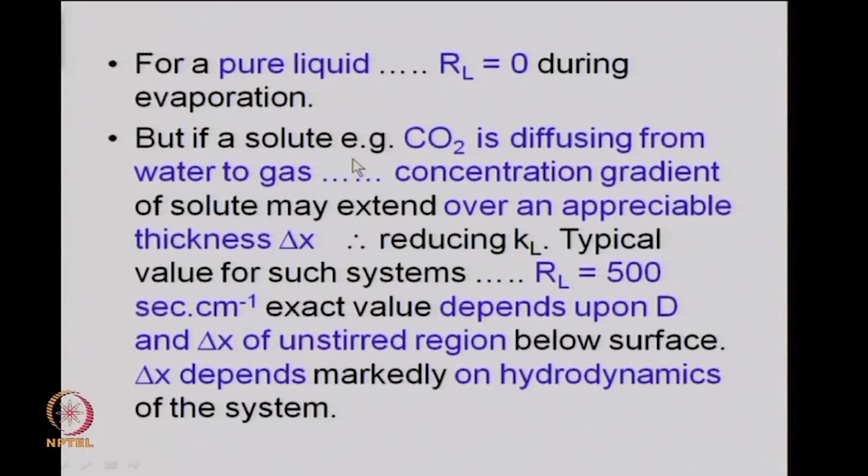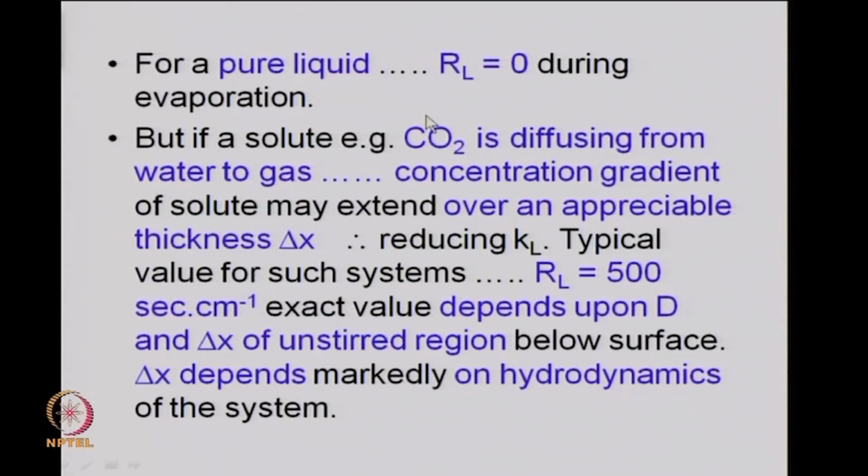Most often you are interested in having certain species solute dissolving and diffusing into the liquid such as water. So, if you take this case like CO2 dissolving and diffusing into water, the concentration gradient may extend over a very large spatial extent. The thickness delta x over which the concentration drop will occur is generally quite large.